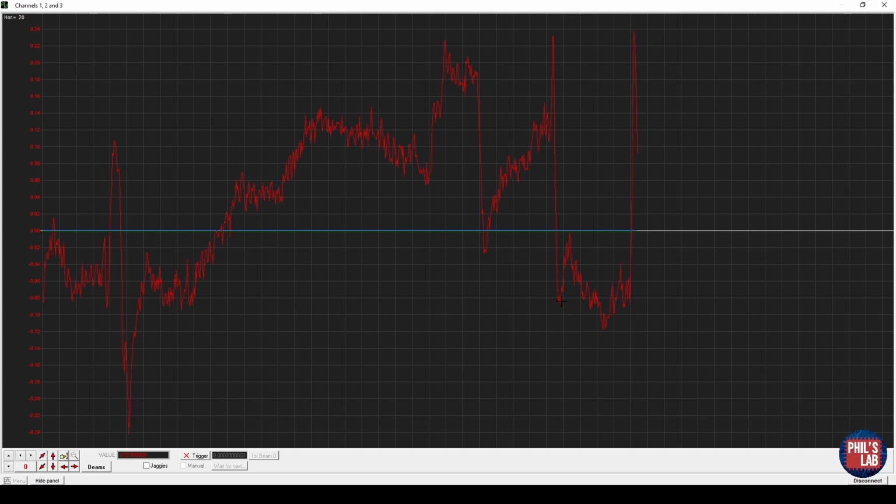Again, just laying the pressure sensor on the table, you can see it keeps trying to climb to a mean of about 10 centimeters. Even though the initial starting point, as we saw on the left, was around 0. So it's definitely drifting away from its center. And we are fluctuating quite a bit. We could, of course, apply more low-pass filtering, and we can also set thresholds. So if it's between 0 and 5, we just clamp that to 5. If it's between 5 and 10, we just clamp that to 10, and so on. So we can probably hard gate this pressure signal, this altitude signal, to get something more reasonable out of this.